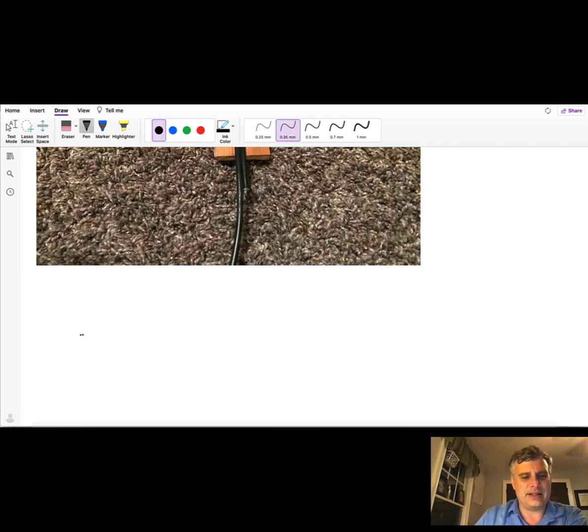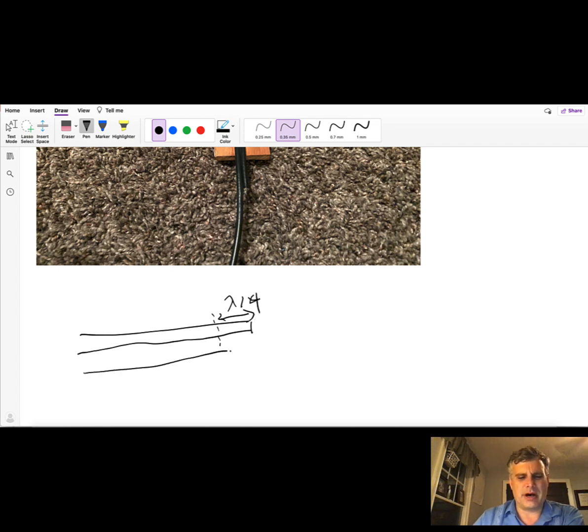And what do I mean by that? Let's take this, and we've got an open circuit antenna line, but I'm going to basically take back, if this is my open circuit, I'm going to cut this off at 1/4 wavelength. And of course, here's the bottom bar for the return current. I'm going to cut that also at 1/4 wavelength. And I am going to bend this back so that now I have the following structure.